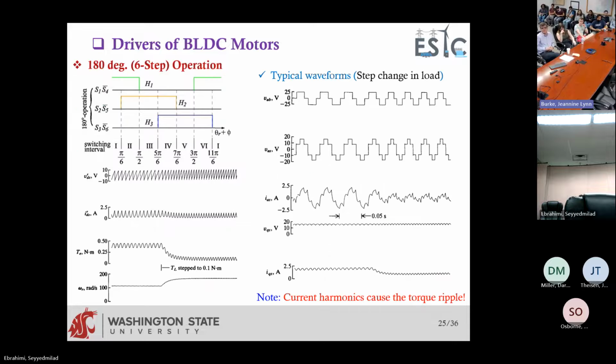And with that, these are going to be typical phase voltages, and these are going to be typical line or phase currents. You see here that this is phase A. I can also move everything to QD, and these are going to be the QD currents, I_Q and I_D, like this.